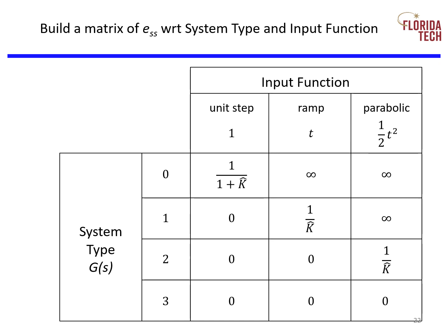Also, we can see that finite steady state errors get smaller as K hat gets larger. Finite errors are on the main diagonal. Above the main diagonal, steady state errors are infinite, and below the main diagonal, steady state errors are 0, which is the best case.